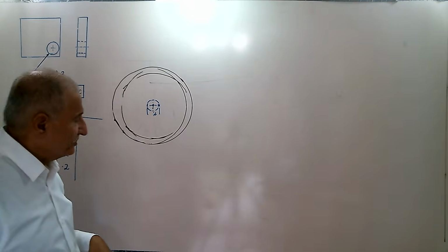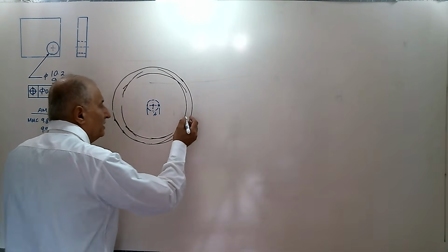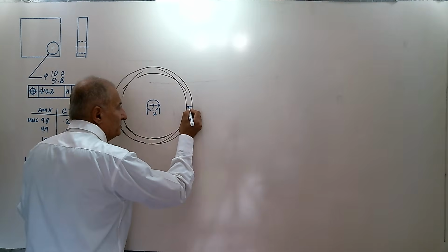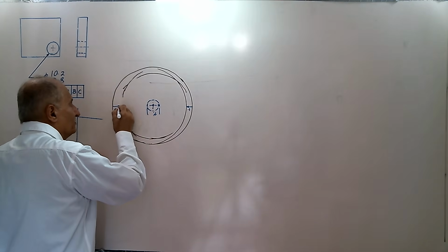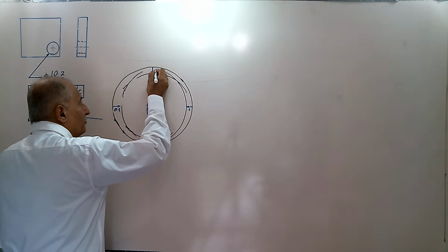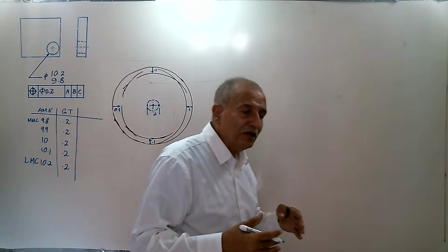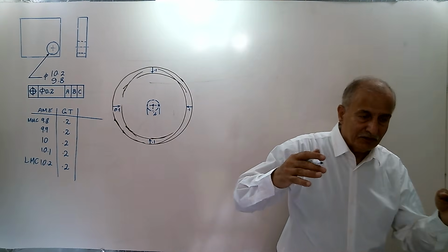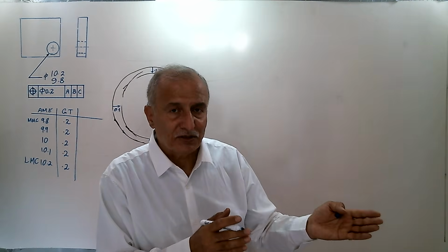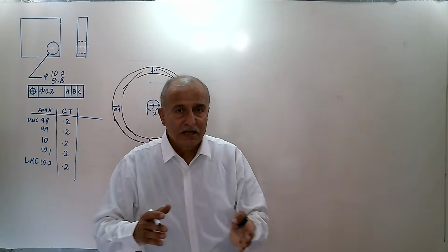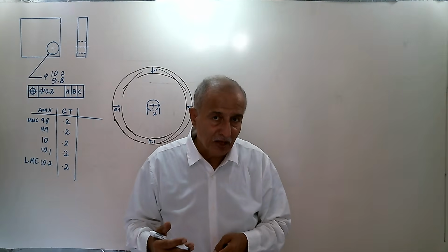Then if we change the center from each side, it is displaced 0.1. This side is also 0.1. Top 0.1. Bottom 0.1. And in any direction that you consider, the edge of the hole approaches one side by 0.1 mm, and on the other side 0.1 inside.